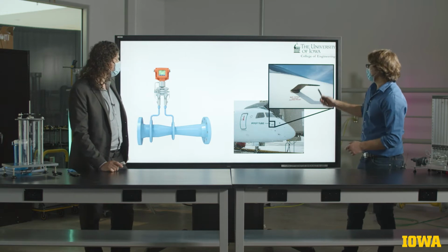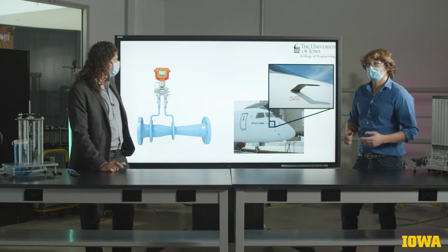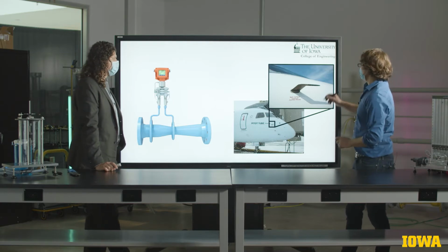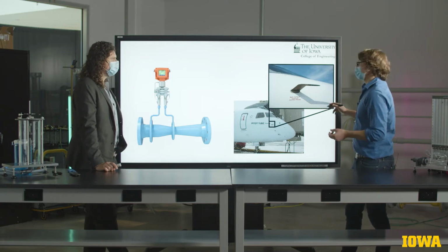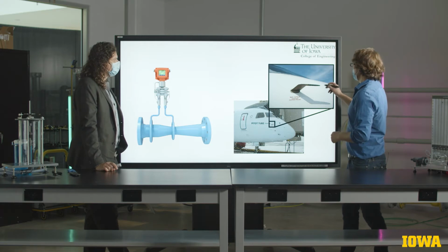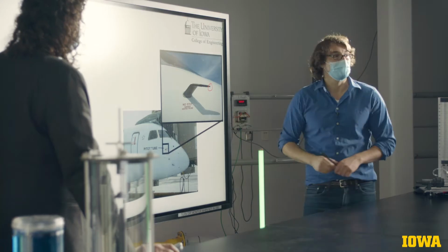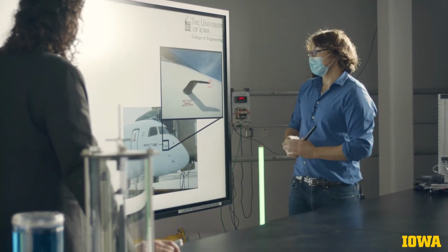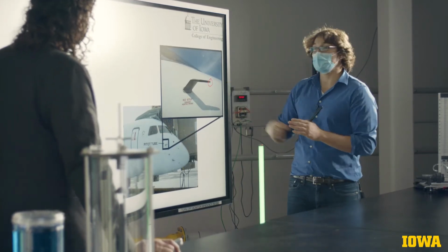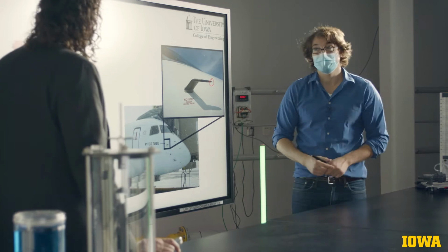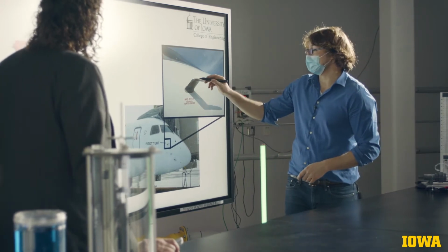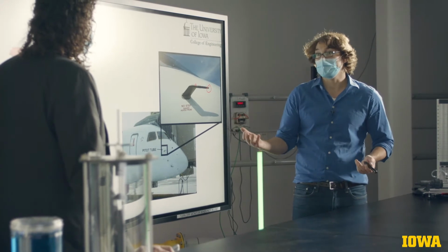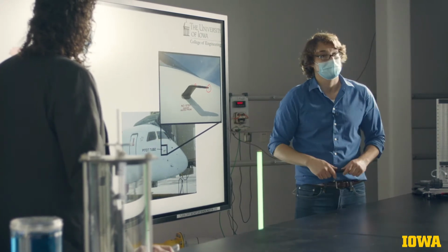The Pitot probe, very similarly, uses the Bernoulli equation, but in a slightly different way. Rather than using a contraction of an internal flow, it uses what's known as a stagnation tube that stops the incoming flow of an external flow, and in that tube measures what's known as the stagnation pressure, which is then compared to a static pressure measured along the side of the probe to get the velocity head from which the velocity can be calculated.